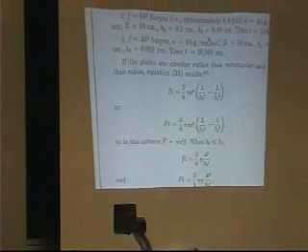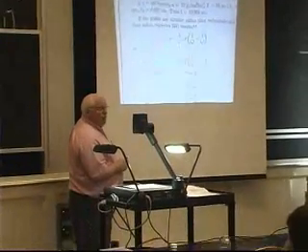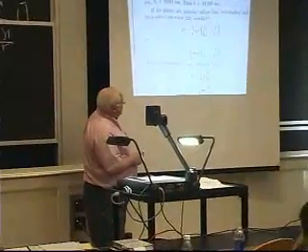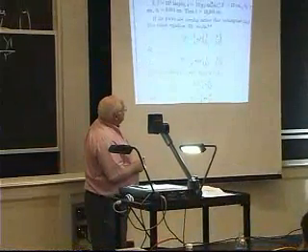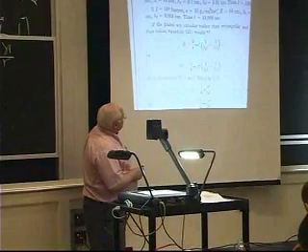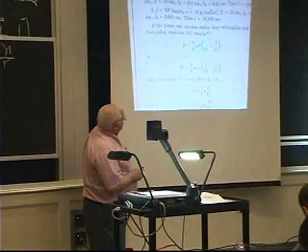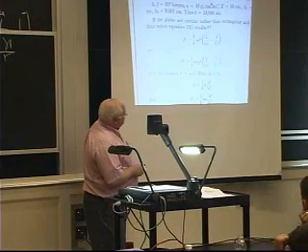That's the formula. So to get it thinner and thinner, I have to apply more force, because this is 1 over h2 squared. The a to the 4th, this is the velocity and stuff. This is just the area of that circular disc. But this is the final thickness. This is the initial thickness.